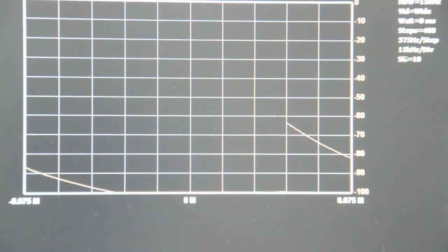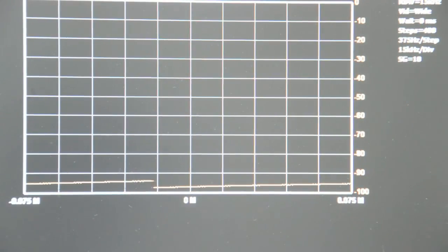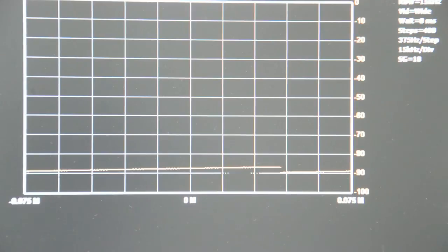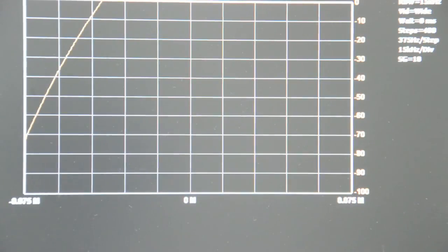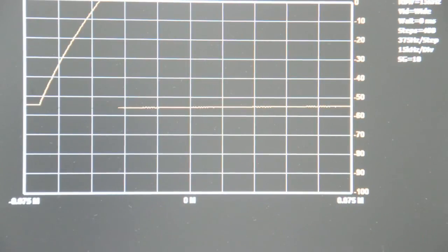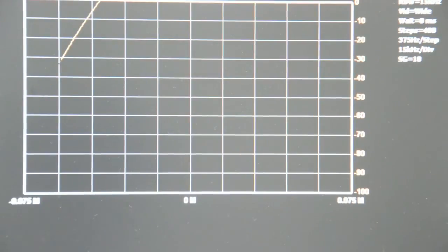It's dropping exponentially, just as you would expect, due to the rules inherent to RC capacitor charging and discharging. Now, if I charge it again, it's rising exponentially, falling, I'm not touching it right now, and rising. So that looks good so far.